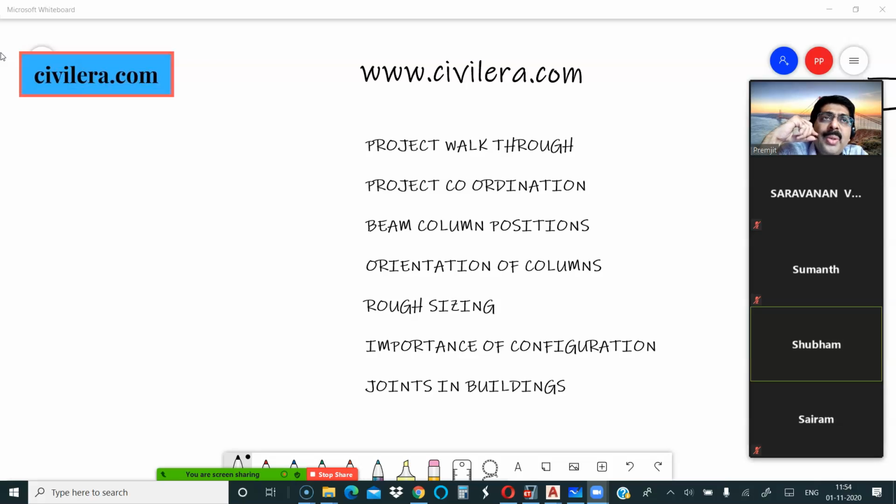Otherwise, everywhere you can tie, you have the possibility to tie. I don't see a reason that you should not be tying it. It's a matter of 2 or 3 rebars, and the performance difference that you will get will be much different. You will get a much better performing building in cases of seismic events and in cases of accidents.